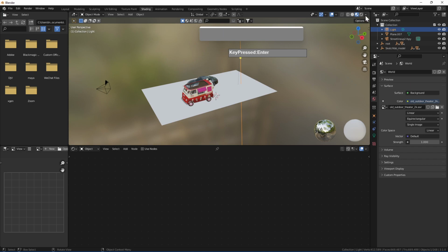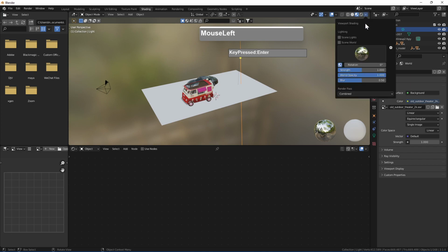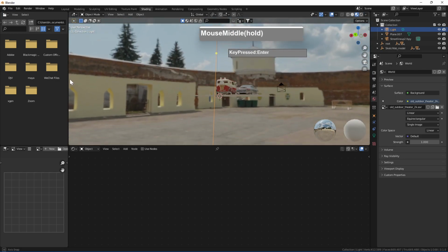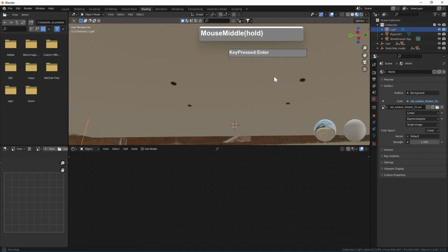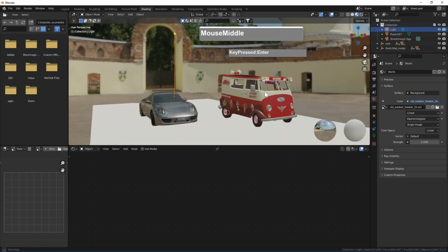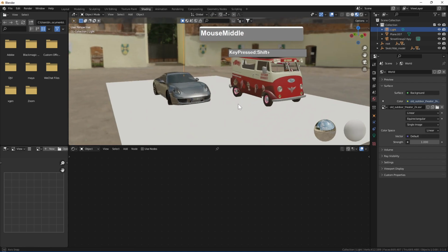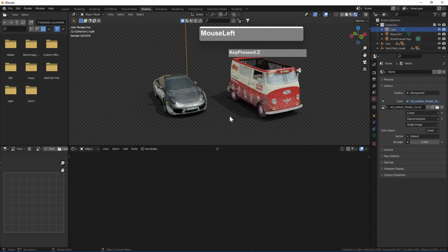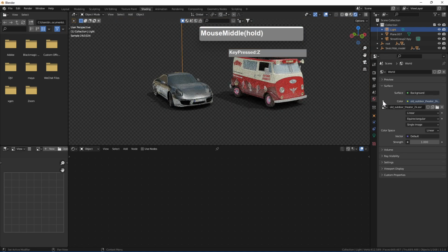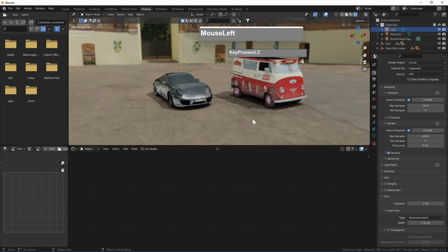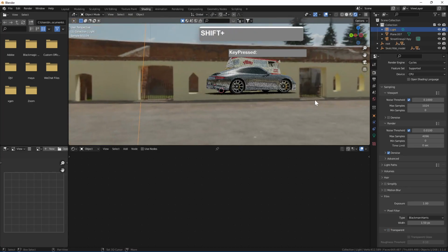And then if you go over to the overlay options for the shading, you can click and change it to scene world instead. And now you can see that our 3D objects are being lit by this environmental HDRI. In order to see that the shadows are correct, you have to change the rendering of the viewport to rendered mode. But because our transparency is on, if you want to see it with the environmental light, we can go back to the render options under film. We can temporarily turn this off, and then you can see where the shadows are coming from.